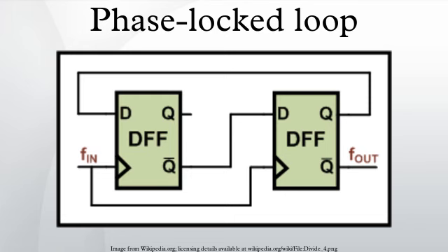As an example, a phase-locked loop implemented using a phase frequency detector is presented in MATLAB, as this type of phase detector is robust and easy to implement. This example uses integer arithmetic rather than floating point, as such an example is likely more useful in practice. In this example, an array tracksig is assumed to contain a reference signal to be tracked. The oscillator is implemented by a counter, with the most significant bit of the counter indicating the on-off status of the oscillator. This code simulates the two D-type flip-flops that comprise a phase frequency comparator.